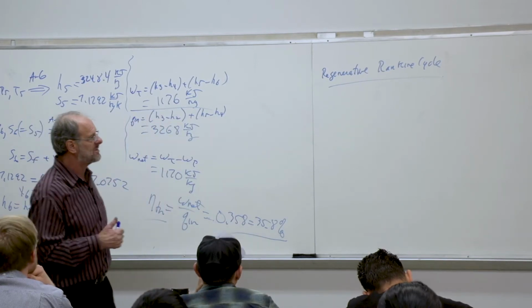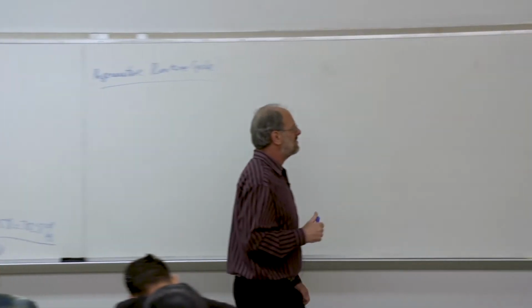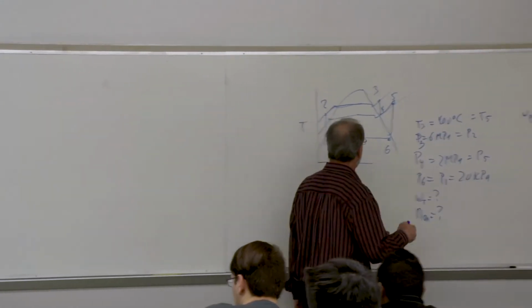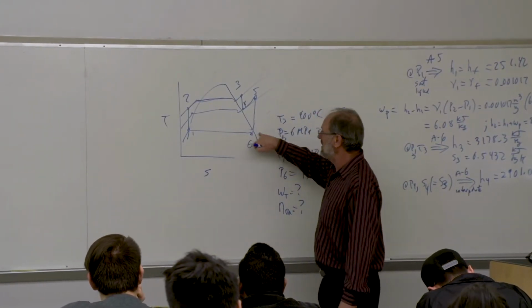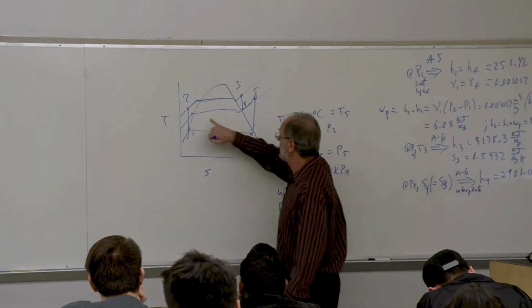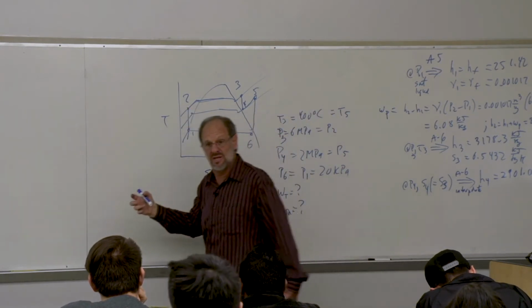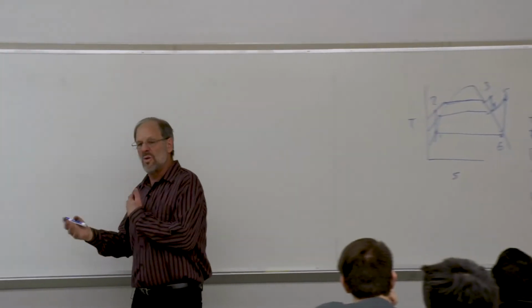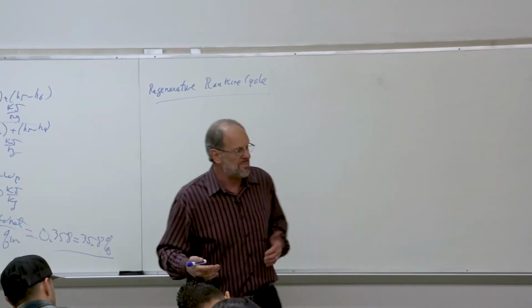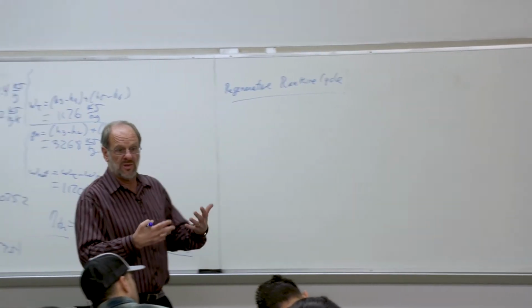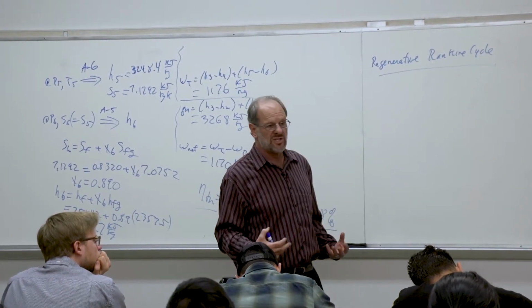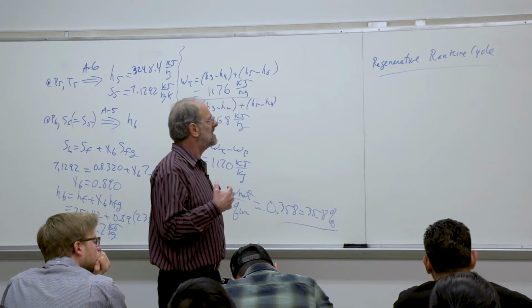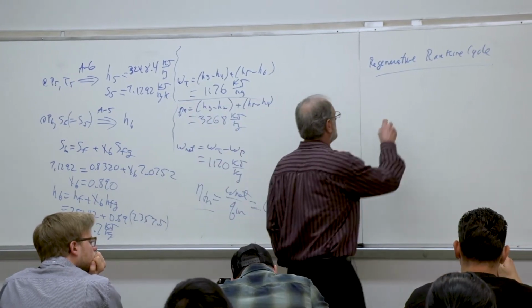We've now seen several TS diagrams, and it should be pretty clear that we can't do that anymore. The temperature as we leave the turbine is going to be very low. The temperature leaving the pump is going to be considerably higher, so there's no way to exchange heat from something cooler to something warmer, right? We need to exchange heat from the warm thing to the cool thing. So we can't use regeneration in the same way. But we can still talk about a regenerative Rankine cycle.